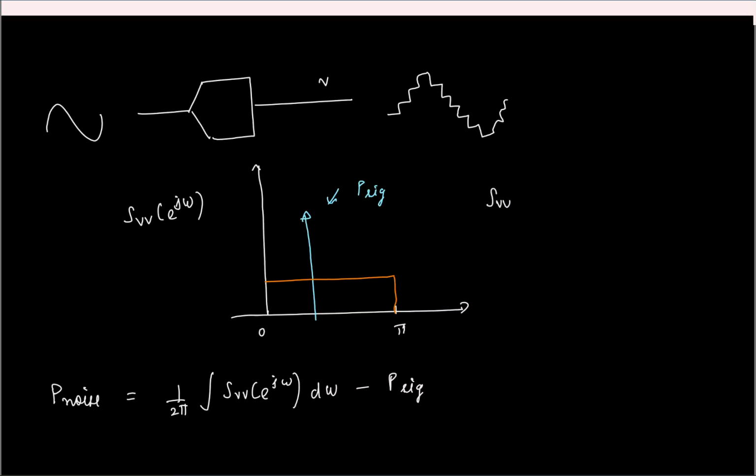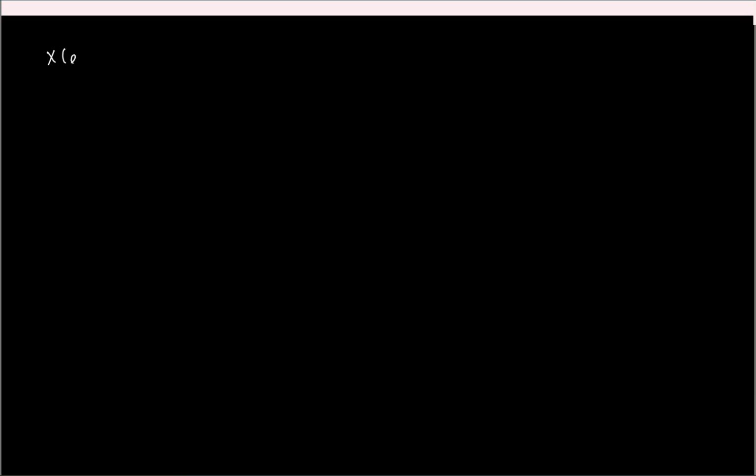And again, mind you, we compute this power spectral density as the magnitude squared of the discrete time Fourier transform. You take the expected value of it, that is, we average it multiple times, and divide it by n. Okay. So this is nice, but one issue is that we have to compute the discrete time Fourier transform. And the practical difficulty with this is the following. If I were to find the discrete time Fourier transform, how will I compute it? Summation from 0 to infinity.